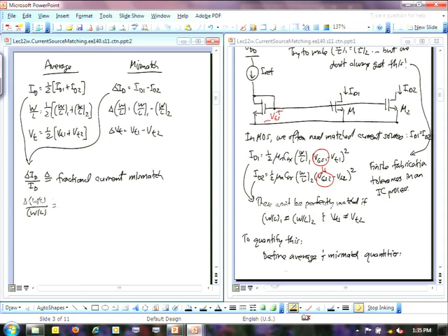To make it easier, I'm going to use the VOV, so I'm not going to write too much. So VOV squared minus 2 times VOV times delta VT over 2 plus delta VT over 2 squared, so delta VT squared over 4. This should be minus, so minus that 2 VOV there.